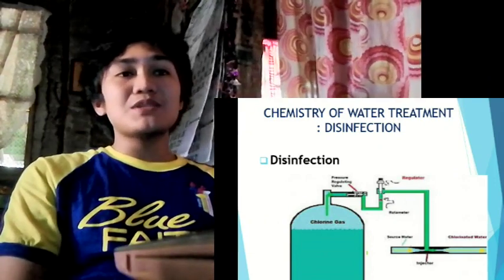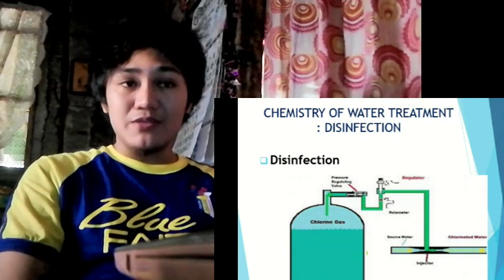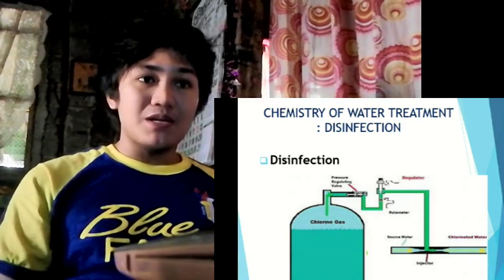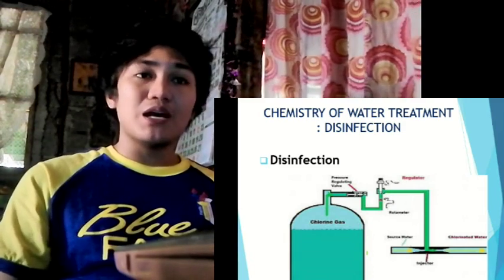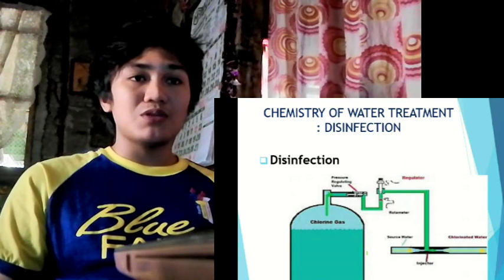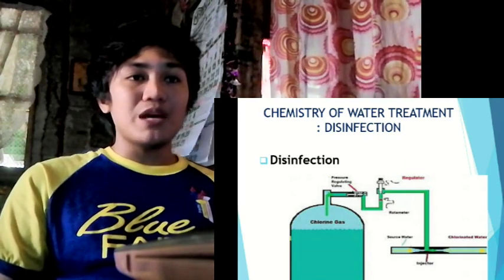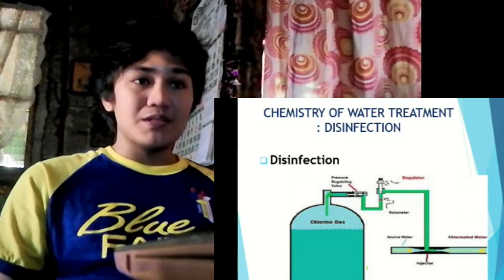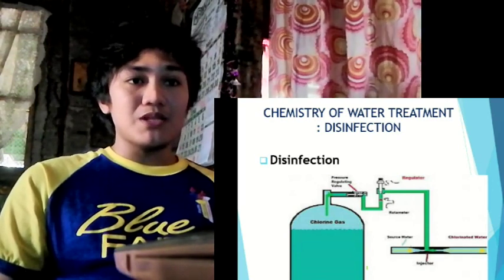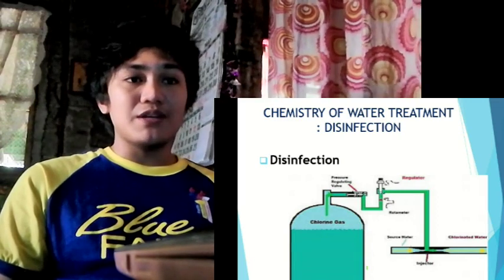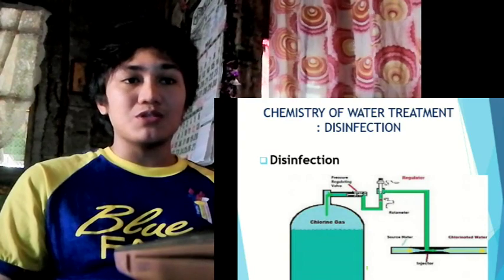To be of practical service, such water disinfectants must possess the following properties. First, they must destroy the kinds and numbers of pathogens that may be introduced into water within a practicable period of time over an expected range in water temperature. Second, they must meet possible fluctuations in composition, concentration, and condition of waters or wastewater to be treated.